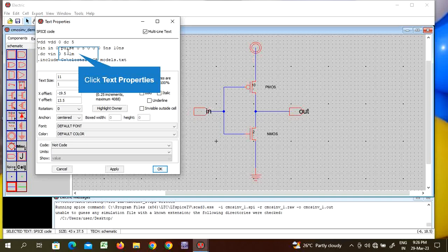Okay, so here please check this. We need to check the waveform now, and here we are giving input in the form of pulses, and that is the reason I'm using the word pulse. Next, what type of analysis are we doing? Right now we are doing transient analysis. So for that, as I said, whether we do DC or transient analysis, we should always start with the dot.